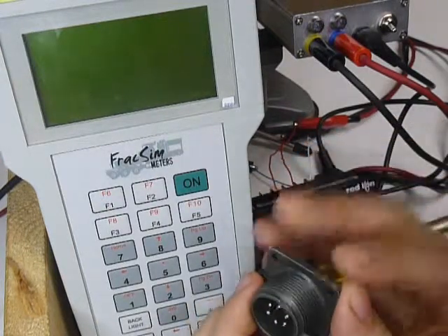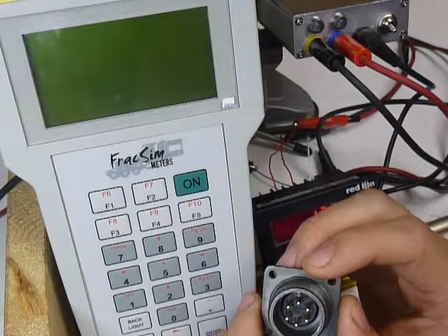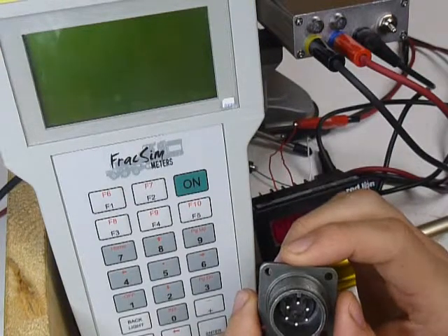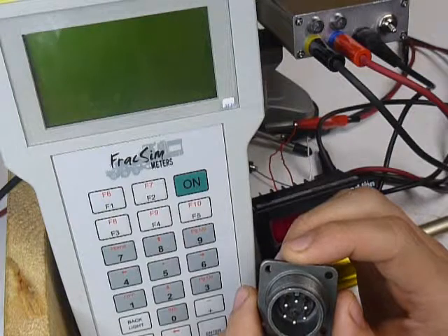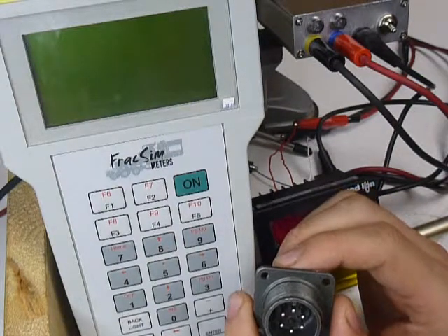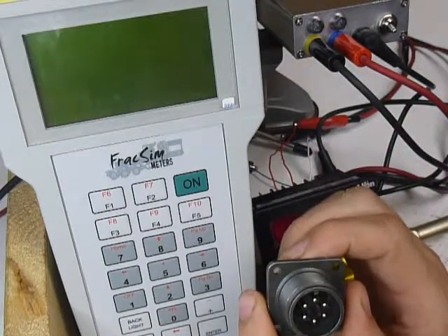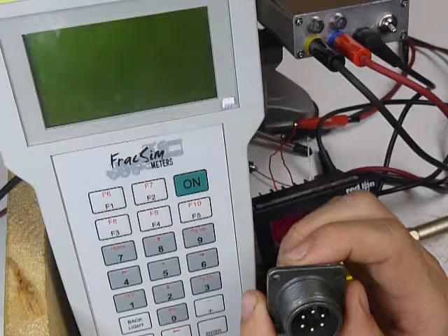And that way all your connections are good and solid. You're not dealing with trying to ram incorrect pins into a connector, especially if you're trying to use the totalizer mode, because if you have just a millisecond of a bad connection, you're going to end up falsely totaling an incorrect value.